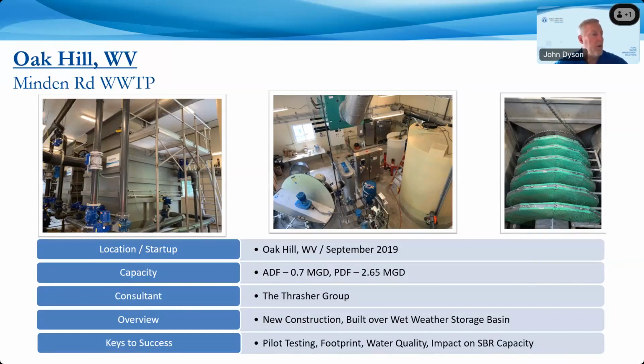In this case, we determined that was about 2.65 mgd. The way to do that without adding any more SBRs, because the site was very constrained, we were able to introduce the AquaPrime technology, and that is removing 80+% of the solids generally from the system in advance. So it allowed us to increase the capacity within the SBRs.